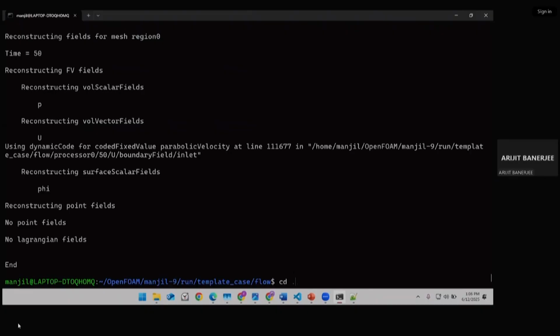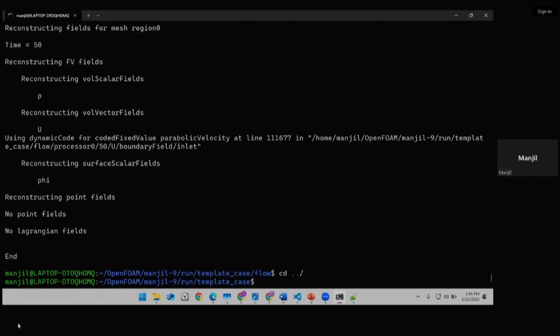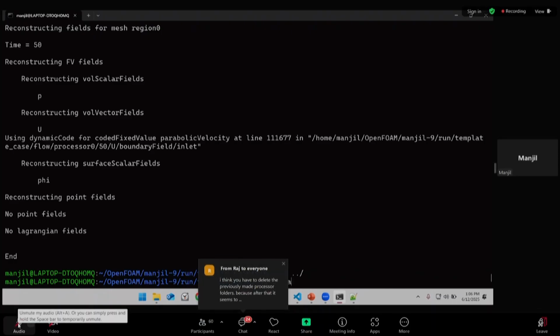While changing that in the Allrun simpleFoam, what should I do with the decomposed part? The decomposed part, it won't reference that file. Okay, now after you have copied the U in the scalar study, now we need to run that case.